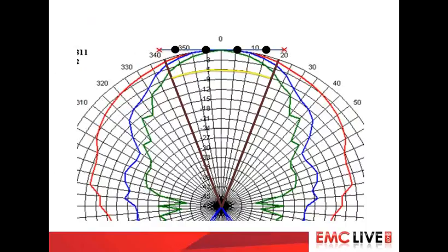Also introduced here is the idea of taking what is actually quite a lot of information in these polar plots that's supplied by the antenna manufacturer, and then sectoring it off into the zone of interest. So the brown lines there are don't care lines outside that area, because the RF isn't hitting the calibration plane, so why should we care? And the yellow line is a defining factor beyond which, if your beam is so narrow that it crosses that yellow line, then you're in trouble, no matter how you try and fix this in a real-life chamber with all the room effects that they have there. You will never be able to fix it, because you've already, under ideal, perfect conditions, overrun the limits given by the standard.